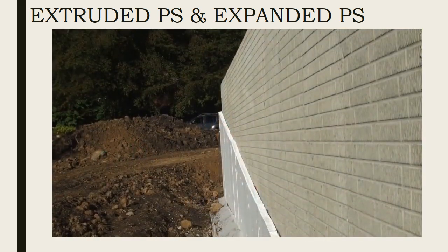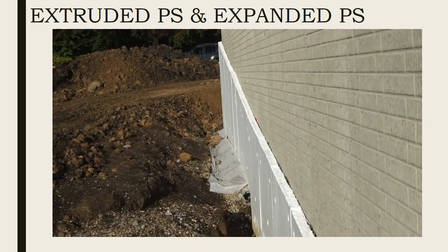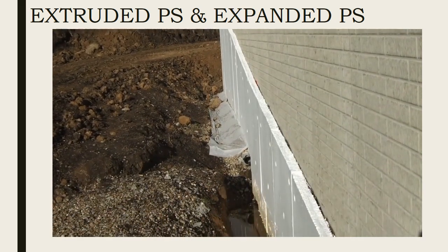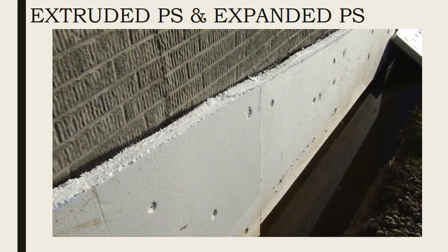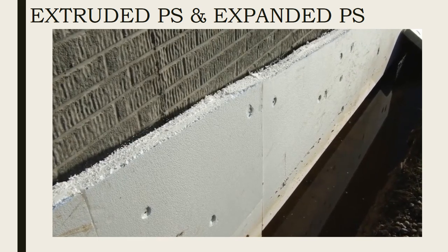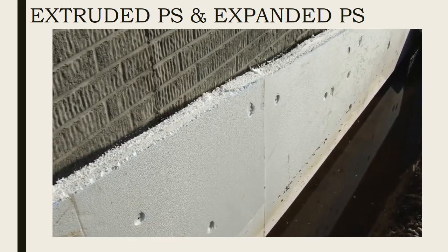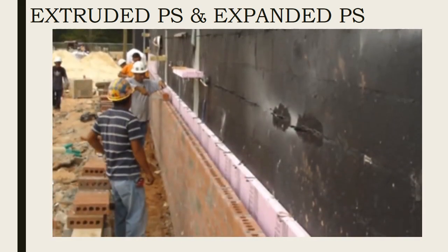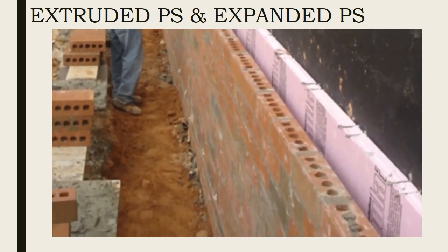When EPS absorbs water, its R value actually decreases, even when tested at lower temperatures. In fact, EPS exposed to water has a lower R value at 40 degrees Fahrenheit than it does at 75 degrees Fahrenheit. This water absorption also subjects EPS to damage during the freeze-thaw cycle, which can have a negative effect on product integrity. XPS continues to have a higher R value at lower mean temperatures even when exposed to water.